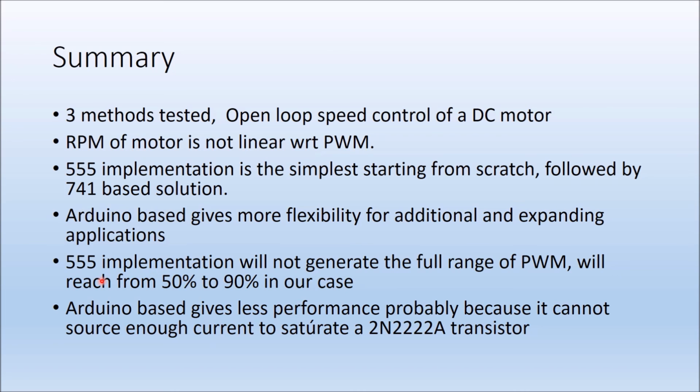The 555 implementation will generate a full range of PWM and will reach from around 50 to 90% in our case. Arduino base gives less performance probably because it cannot source enough current to saturate well transistors such as the one we've used here.